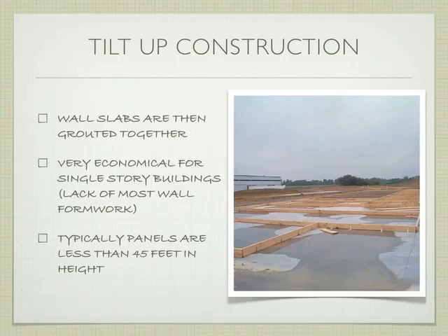So here's our examples. Here's our perimeter edge form right there. Obviously, some of this kind of stuff concerns me. We've got all this water. That's not a good thing. Hopefully it dried before they decided to pour the concrete. So they lay out these forms, and then these are ultimately going to be the walls that you're going to tip up into place. They'll spray a form release agent to make sure that they separate.